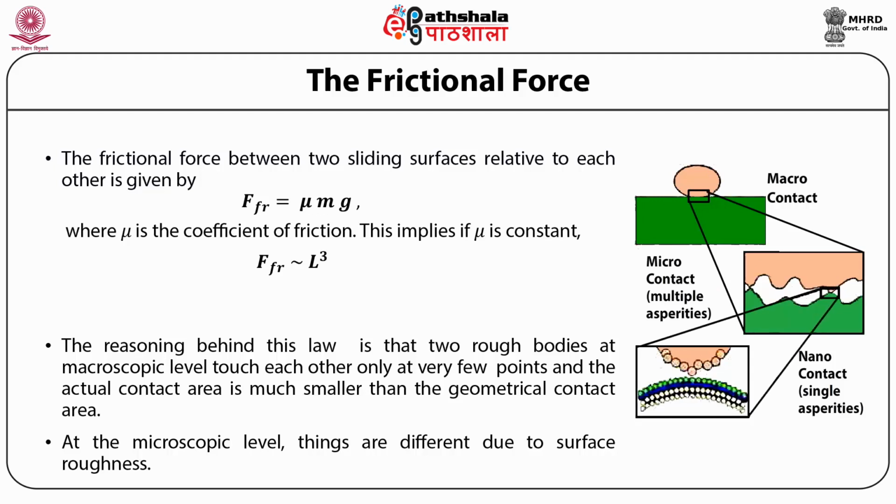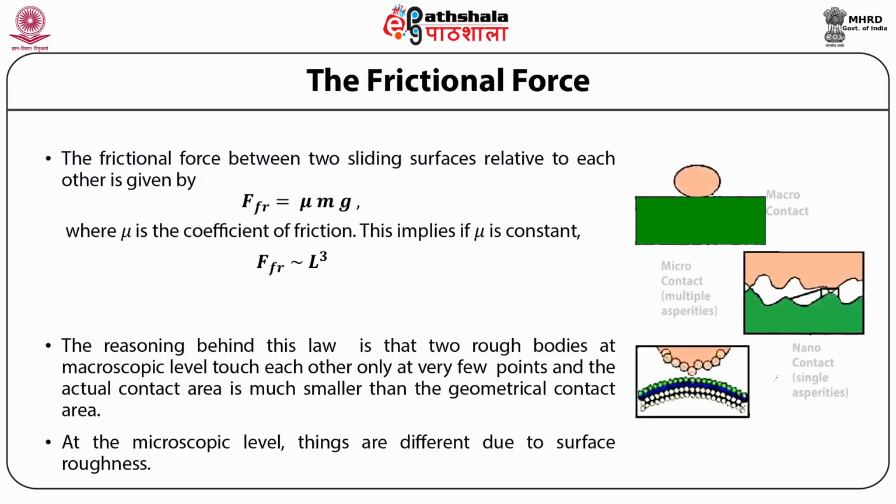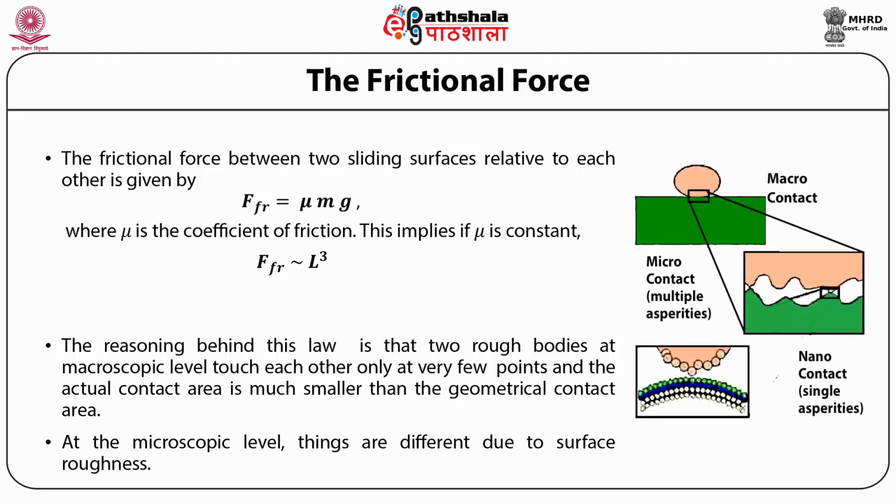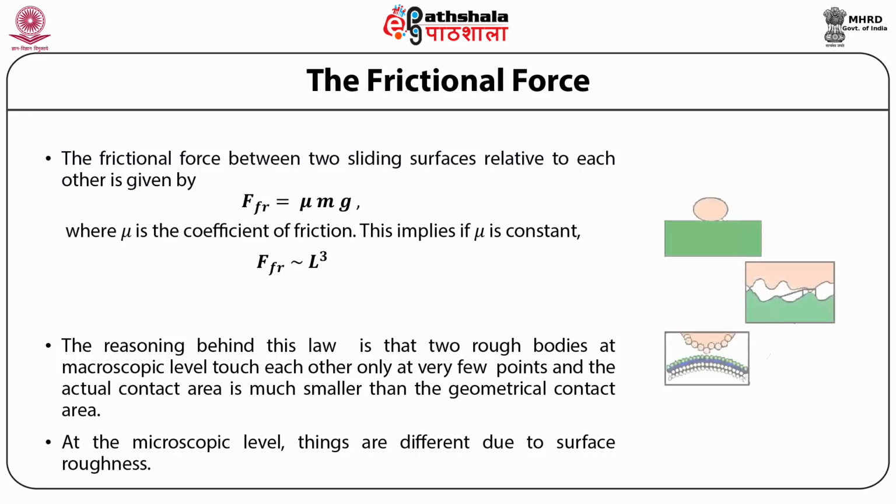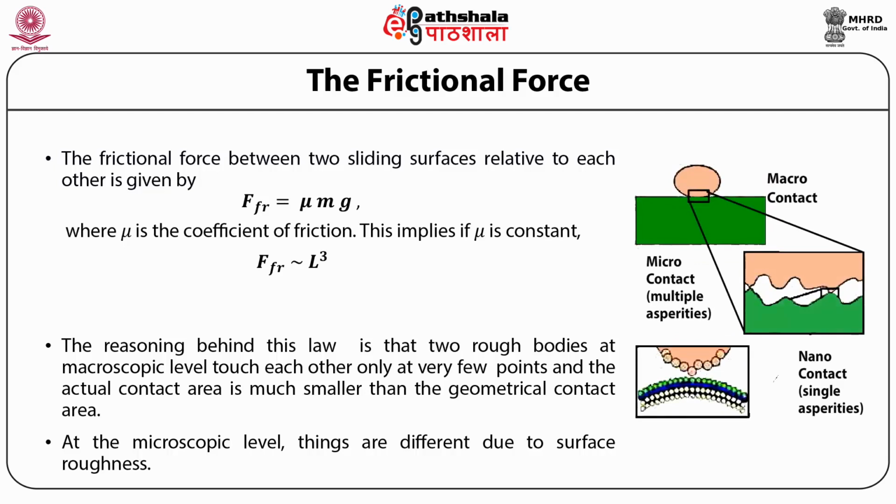The tip in AFM is a well-defined, sharp, pointed contact which enables us to measure the interaction forces with nanometer resolution.